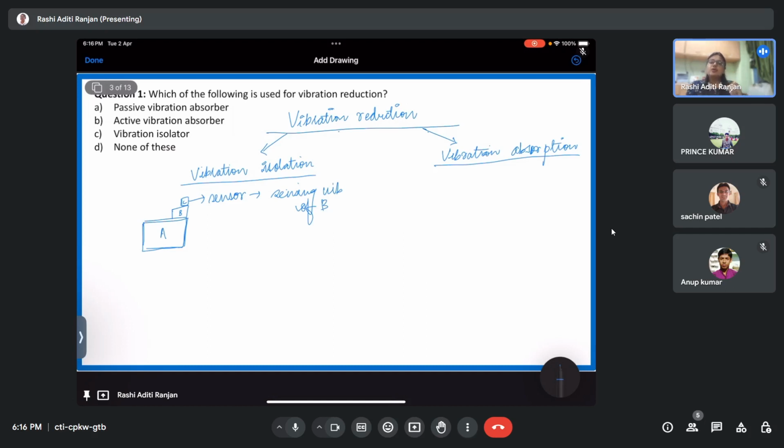Now the sensor C is going to sense the total vibration, the vibration of B as well as the vibration transmitted to B because of A. So I need to apply some isolation between A and B so that B is vibrating only because of its nature, not because of the transmission of vibration produced in A. If I don't isolate B, then B may vibrate at some other frequency, or have two frequency components, which is not true for it. That is why some kind of isolation is required.